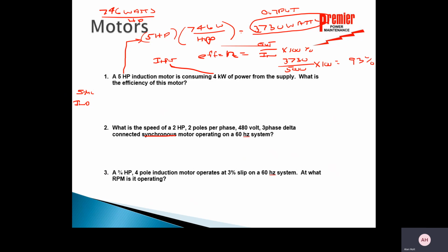So there's always a slight difference between the speed of the field on the outside and the speed of the field on the inside, because there has to be some attraction there. There has to be a difference. If they were totally in sync, there would be no torque available. So for a synchronous motor, it has to operate at synchronous speed.